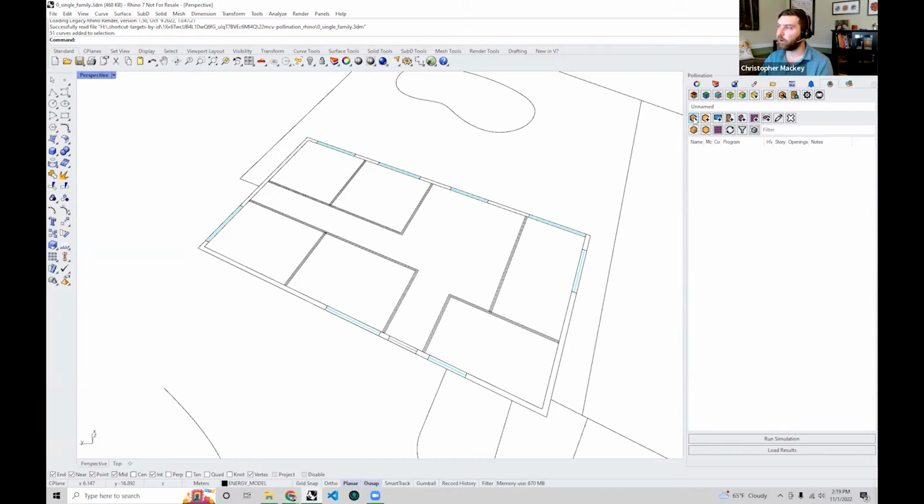If you left click on this little add rooms button, you'll see that there are a few different ways that you can create rooms. You can select some actual detailed geometries, which we'll get to in a second. You can select geometries by layer, or we can do this last one, which is drawing a room. So that's what we're going to do right now.